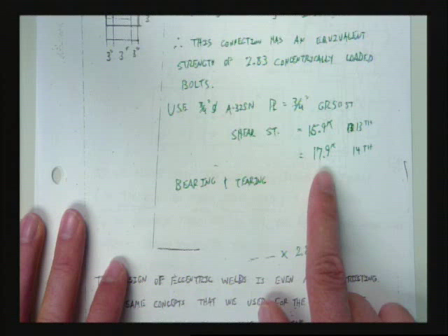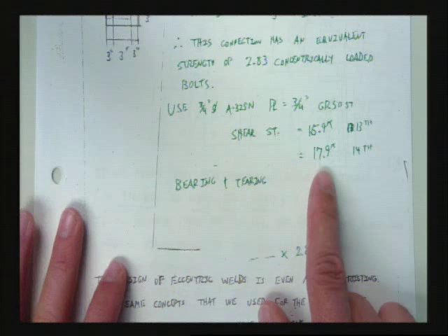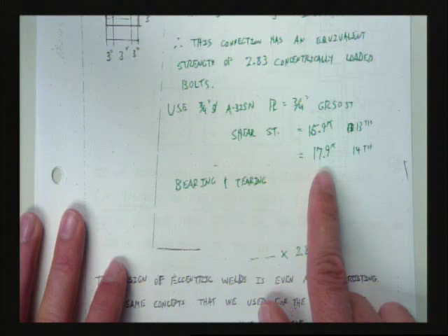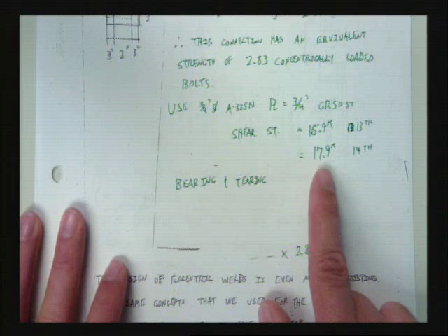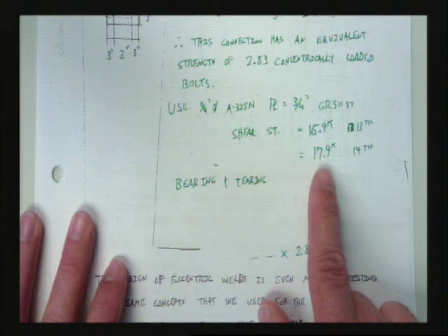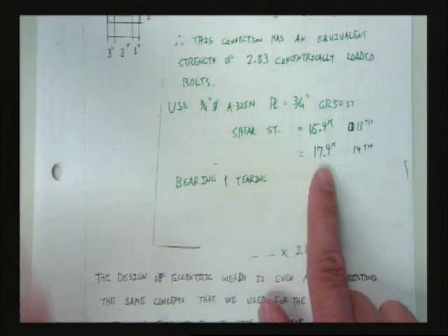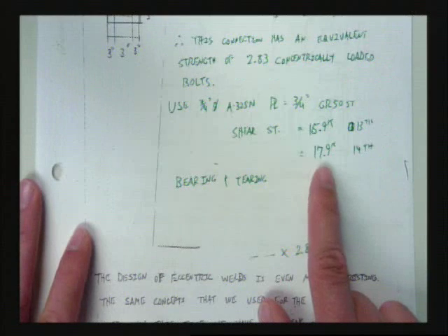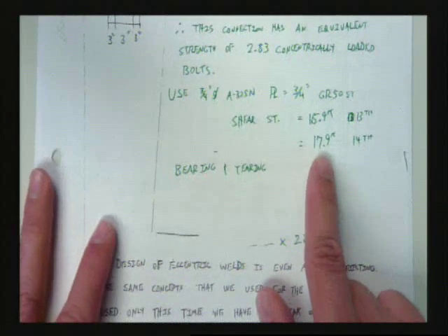Remember, there is a continuous war between all industries to shave out as much safety factor as possible so they can sell more, right? Because the bolt people are fighting the weld people. If they're able to shave out some safety factor, they're going to be more competitive with welds. That's what happened between the 13th and 14th edition. Now, they may tell a story differently. They may say, oh, we re-examined the safety factors provided by our past tests, and I'm not saying that's wrong, okay? But they've convinced people that their bolts are stronger. That's what they did. 17.9.